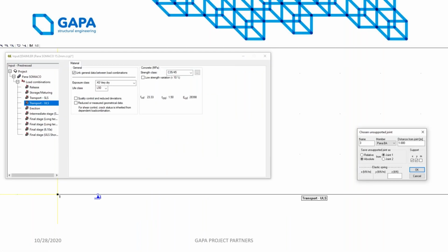Now, coming back to what I was saying earlier, it's important to treat the initial phases of precast element's life with care, especially when you're working with a new precast fabricator. Communication is important and helps ensure that the assumptions that we make during the design coincide with the conditions that the elements will encounter during striking, storage, lifting, and transportation.